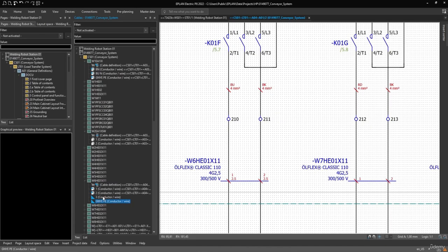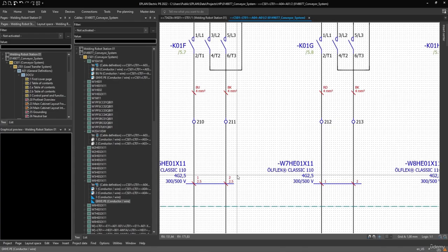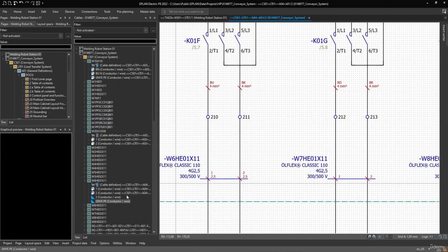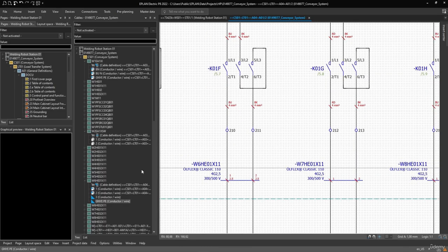So I wouldn't suggest you to select a cable and not use its core, because then you have a lot of cores that are lying inside your panel that are not being used. So I would rather maybe select 3G 2.5 and maybe ground the third wire. So that's what you can do with your cable navigators. You can use them like that.